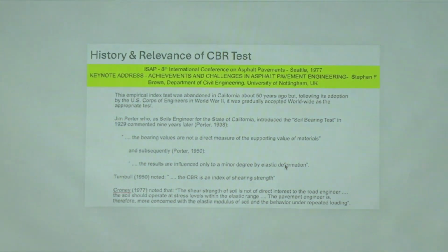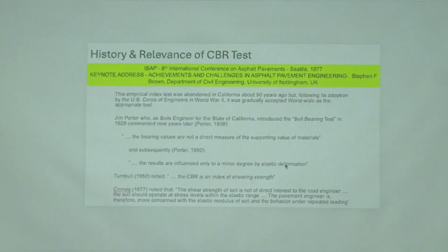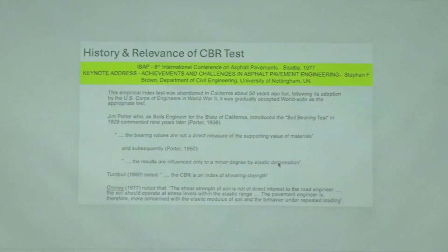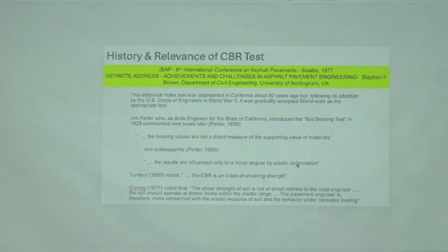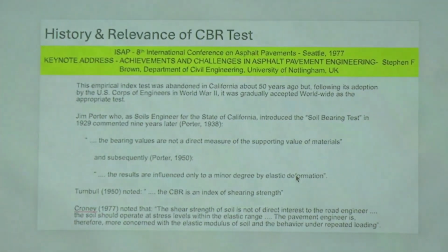to predict modulus, right? So the person who developed CBR said don't do it, but after World War II it was widely accepted, and that is the reason we keep doing it.